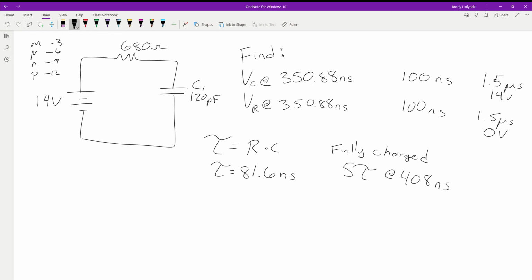So we know it's going to be in our range. 4 tau is 98.2, 5 tau is 99.3, so we're looking somewhere in the 98.7 range, just roughly as an idea for what our voltage should be. Because we're not quite fully up to that 5 tau mark, but we're above the 4 tau. So we should know at least the range that our answer should fall in.